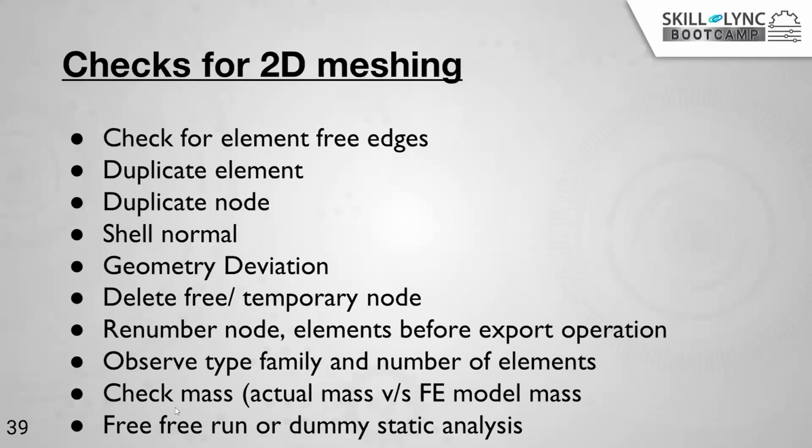You are carrying out FE analysis to capture the physical phenomenon in a virtual reality. So what is there in the actual condition should be matching. The mass of the component in reality should match the FE model mass.